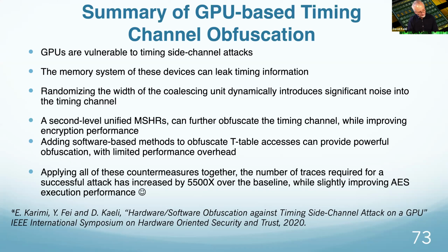So generally, you need tens of thousands or hundreds of thousands of traces. If this is 100,000 and this is 5,500 more x, we're talking 5 billion. So this makes it so robust to attacks. At that point, the effort to do that is just too much work, and in the time it takes to recover the key, you can easily change your keys.